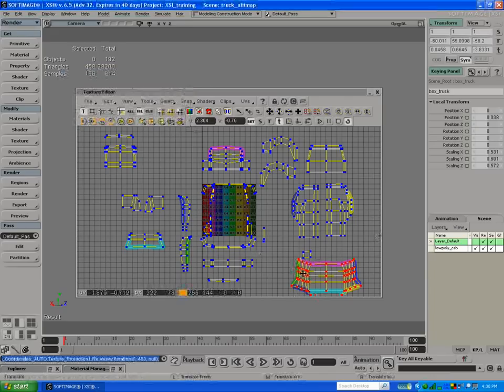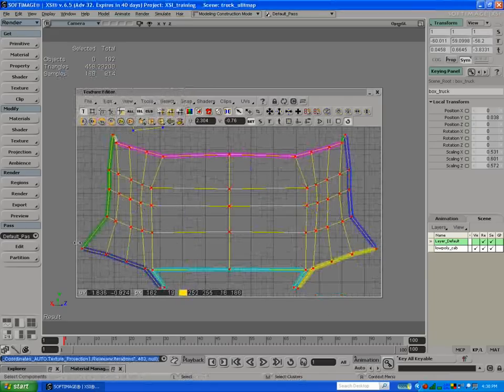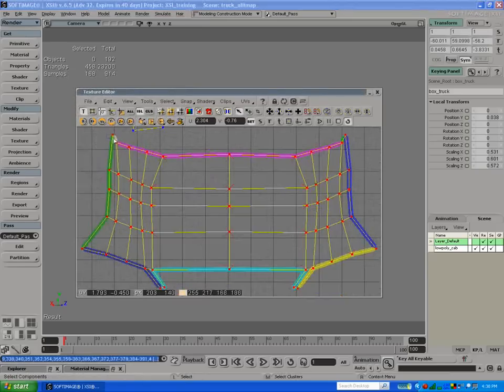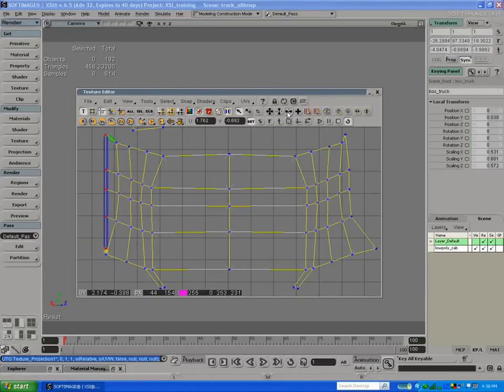You can also go in and just frame that. What I normally do is just go in and pick a series of points, turn the island off, just pick a series of points, and start using some of these tools here to kind of collapse them and straighten them into nice straight sections.